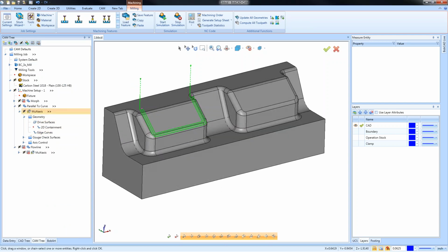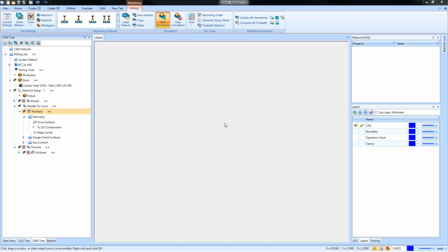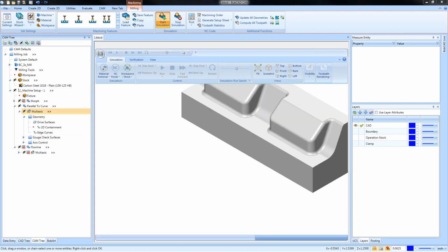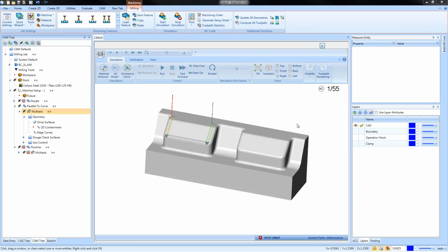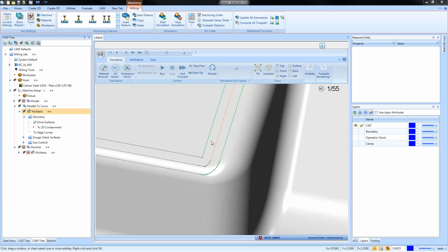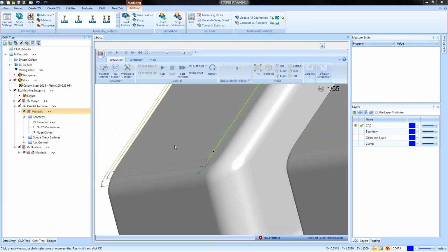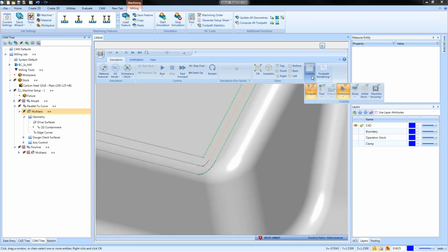That's the toolpath. When we get into simulation, I have the ability to check what the points are in backplotting. I can click through it and see what they are, but it's a little bit easier to see what's going on here in simulation, because we can show our toolpath points.